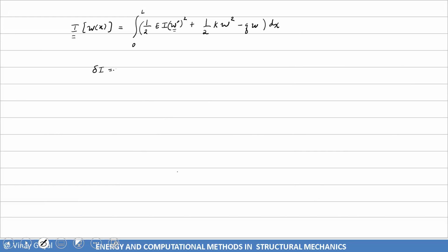Okay, so let's look at what I just said in a graphical format to make sure you understand, because those words are extremely important to this class. This is the functional of interest that I came up with. And this idea that we're discussing, to me, is an amazing idea. If I want to find the function w that minimizes I, I set the first variation of I equal to 0. That will give me the governing equation I just showed you earlier. So let me type it here.